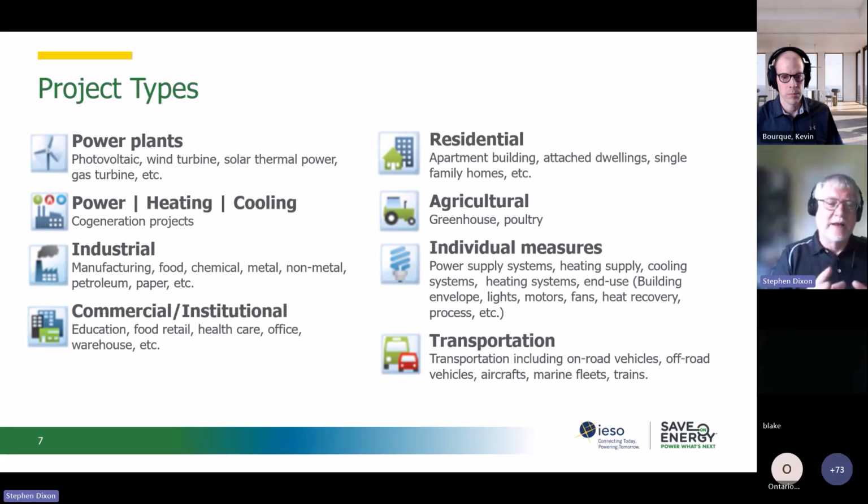But the way we use RETScreen is we look at the situation and think about what's going to change, what's going to cause the energy savings. And you realize if the temperature at the ceiling becomes cooler when you destratify the air, there's less heat loss. So all we have to do is model the heat loss with the building envelope model in RETScreen and the temperature schedules. We can model that pretty easily. So analyzing a project in RETScreen comes down to abstracting that physical situation and representing it within the tools that we have.